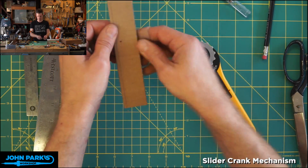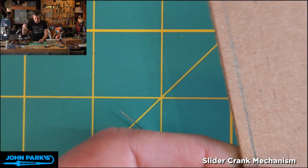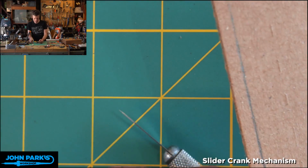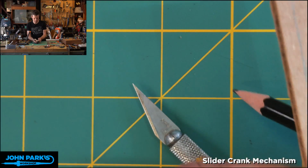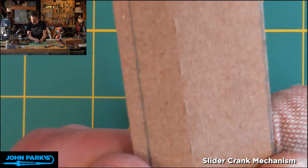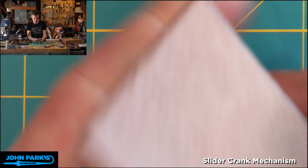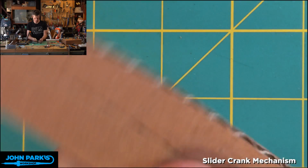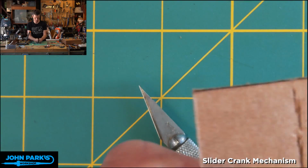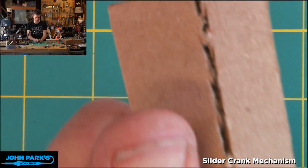So now I've poked, let me pop over to this camera. Now you can see a little bit there. I've poked into, as I bend this, you'll see little perforations there. And so now it's very hard to bend these in the anti-grain direction until you cut or perforate.